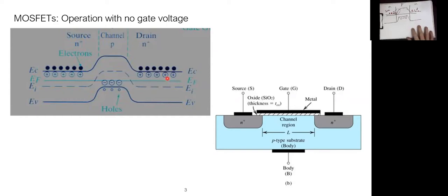Okay, so what is next? Now we are working toward pushing the electrons to move from the source to the drain. So we need to get rid of this barrier. In order to get rid of this barrier, it simply means pushing this P region downward so that you can get this barrier out.